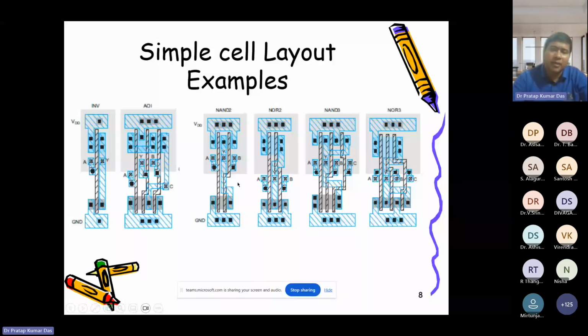Now there is something called electromigration. When a cell goes through thousands or lakhs of cycles, it creates damage in the cell. Like if you have a piece of metal and you rub it and use it several times, even in wires, you would have seen after 10, 15 years, it melts. Because these cells conduct a lot of current. Ultimately, it's a piece of wire, like the wiring in your house. So the piece of metal which carries the maximum current goes through maximum wear and tear. So the key takeaway here is that these common output nodes you need to make thicker compared to the ground and VDD ones. Okay. So now if I come to the NAND 3 input, I hope you can understand that.